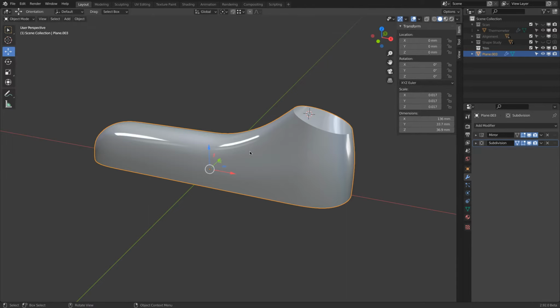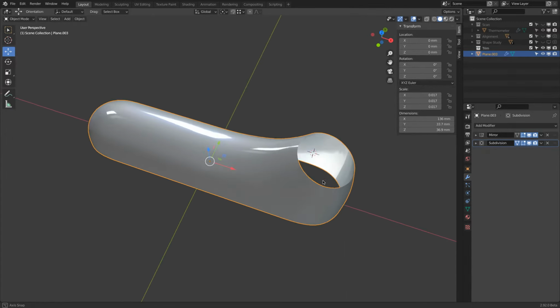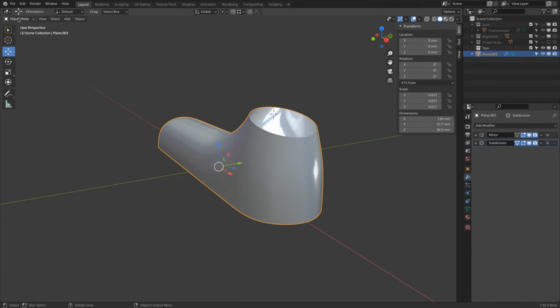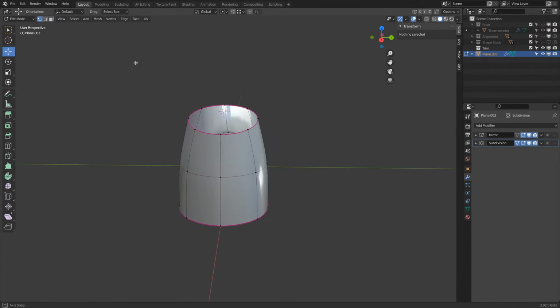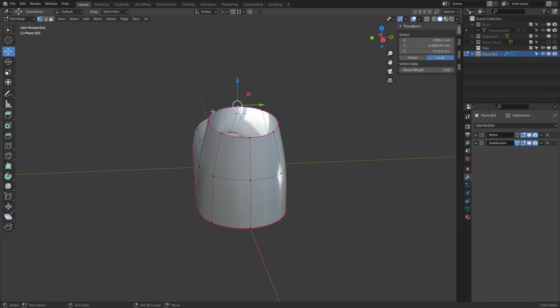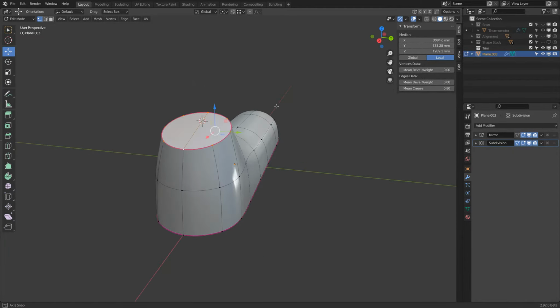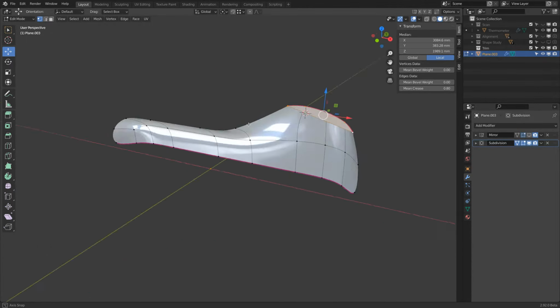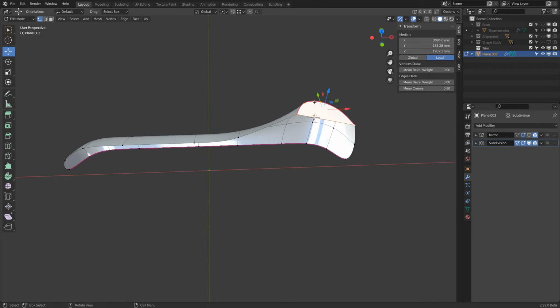The only thing that's left to do is put the cap onto this opening and the bottom, and then put in the interface elements. To do this, let's go to edit mode. And when we select all these points and press F, we get a filled surface. Again, keep in mind, because this is half a model, initially we only select half of the ring, and then when we press F, it puts a middle line in and fills it.